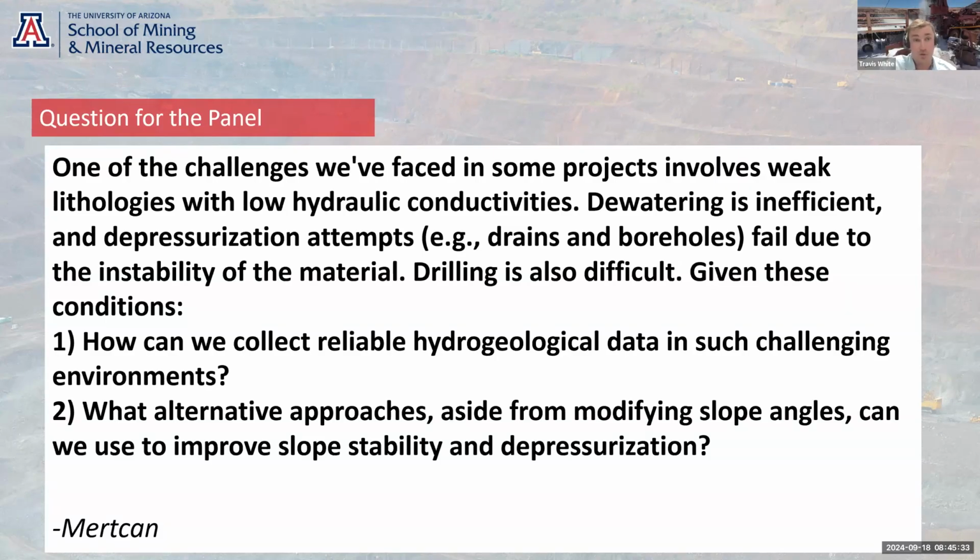Yep. So good question. When you're dealing with a weak rock mass, or anything that's clays and tillites, or saprolites, things that are notoriously difficult to drill through, it's the drilling technique that you use that's important, right? You won't get away with your normal DTH percussion, diamond or RC. That's when you've got to use techniques like symmetrics or drill and drive, or sometimes sonic drilling, so that you're able to get the hole in and then get the relevant support inside the hole to keep it open.